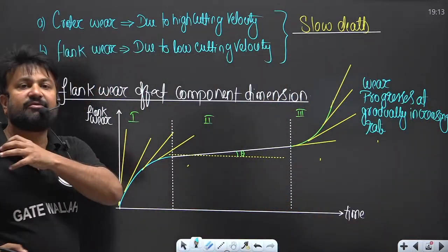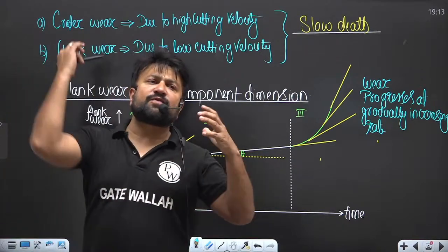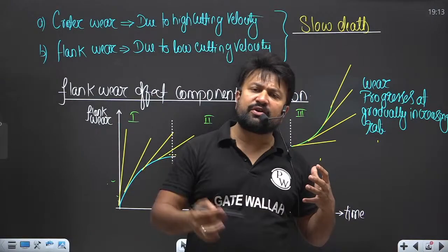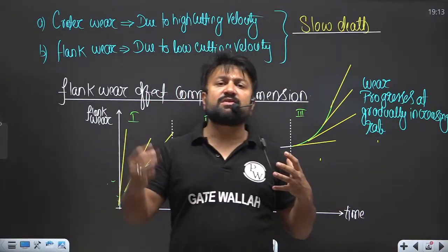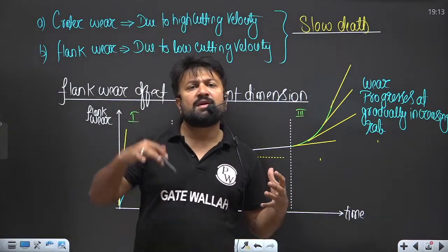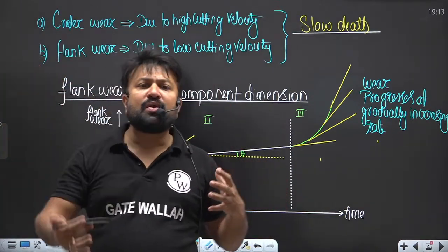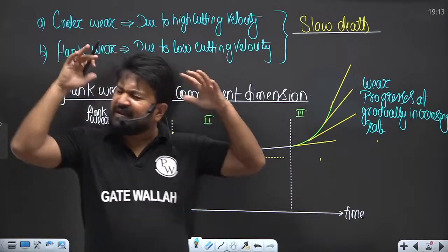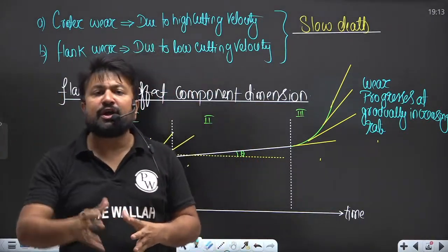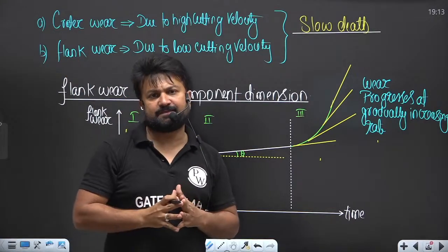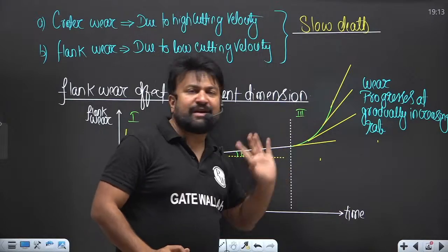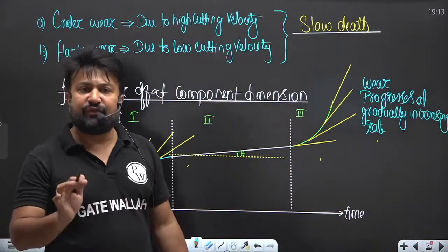Why? Because from the beginning the tool is continuously cutting, so temperature goes on increasing. So in this tertiary region, the wear of the cutting tool has become sensitive to the increased tool temperature due to high wear length. So generally we don't recommend going into the tertiary wear zone.